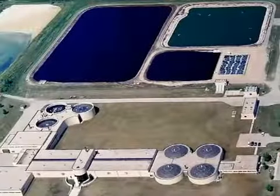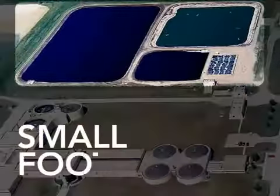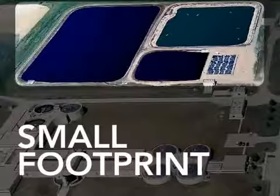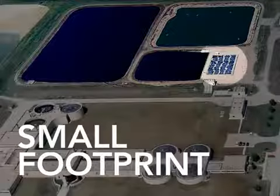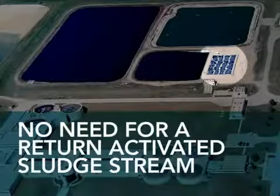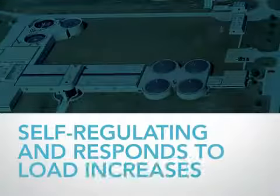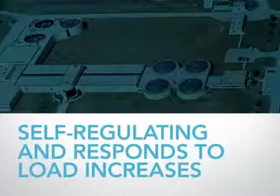With the MBBR process, operators can maximize treatment capacity while minimizing their footprint. An MBBR system is a fraction of the size of a conventional system and can be built without the need for a return-activated sludge stream, allowing for a single-pass process. Additionally, the HeadWorks Bio MBBR biofilm process is self-regulating, automatically responding to fluctuating organic loads without the need for operational